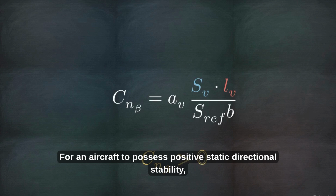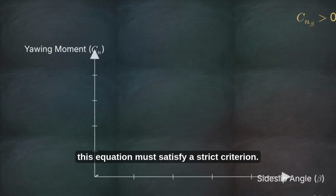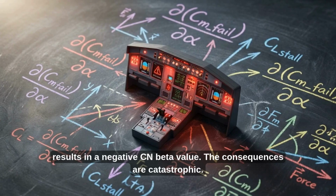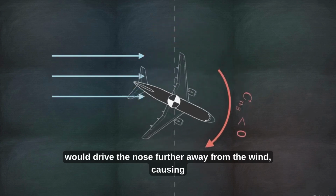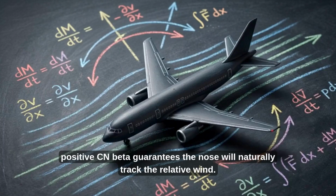For an aircraft to possess positive static directional stability, this equation must satisfy a strict criterion. The yawing moment coefficient must increase positively as the side slip angle increases. In mathematical terms, Cn beta must be greater than 0. If an engineering flaw results in a negative Cn beta value, the consequences are catastrophic. The moment the aircraft is disturbed by a gust, the aerodynamic forces would drive the nose further away from the wind, causing the airframe to actively try to fly backward. A positive Cn beta guarantees the nose will naturally track the relative wind.